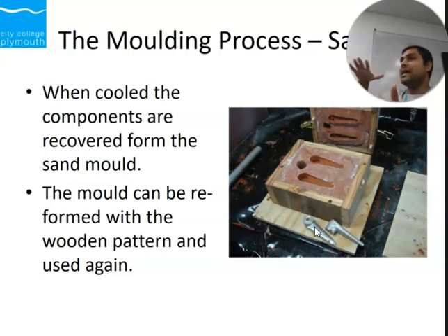You just have the sand, and in the sand you put half of the mold, and just level the sand, press it, and then you do the same on the other side of the mold. You put both halves of the mold together, but before you put them together, you arrange a channel for the flow of the metal, the runner and the riser, and so on. Between them, you spray solid graphite to make sure the metal does not stick to the sand.